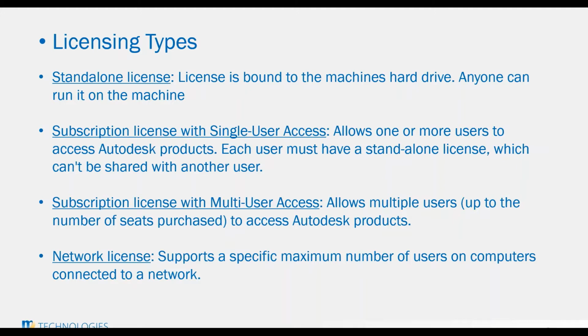I will get into that a little later in the demonstration. But what's happened is that there are multiple local licensing components installed on the system, and it's very possible that these do not start. One of them may not start. I believe there are 3, and if one of them does not start, it will produce an error message. From there, a simple reboot may cure it. That is the first suggestion we usually give people.